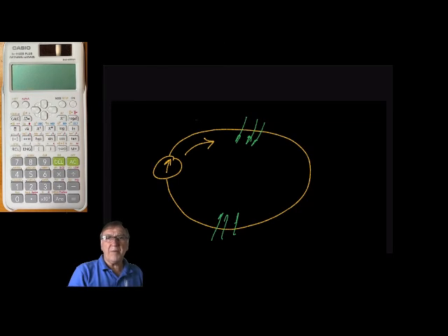Next thing I'd like to talk about is the right-hand rule. The right-hand rule describes how the magnetic lines of force align with current flowing in a conductor. I have this pen here. I put my right hand on it, my thumb points in the direction of current flow, and my fingers show the direction of the magnetic lines of flux.